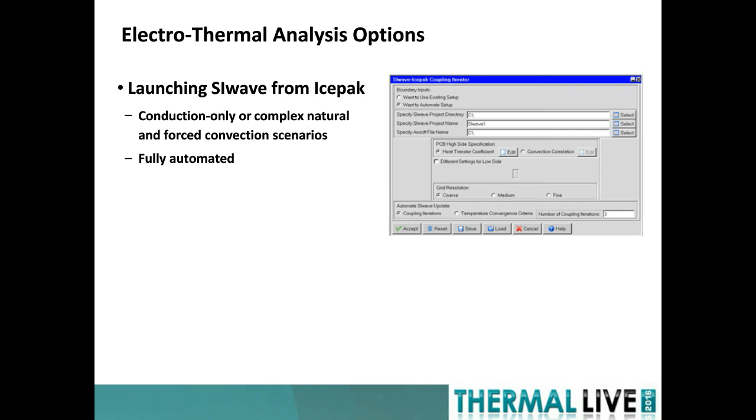A more broader question here. A user is wanting to know what's the best way to find the convection coefficient of the surfaces in the model. Yeah, there's a few different ways to do this. One way is just to run a CFD analysis. If you're running CFD, you don't need to worry about specifying a heat transfer coefficient.